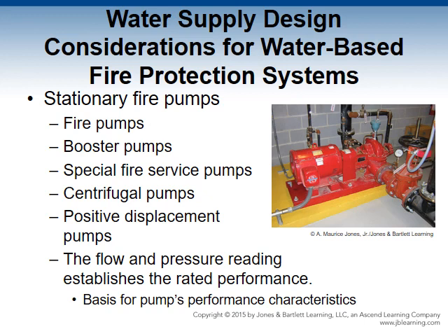Stationary fire pumps. When water-based fire protection systems have adequate supply but need additional pressure and flow of water, the stationary pump is usually the first and obvious option. The fire pump has replaced the gravity tank and water booster pumps as the most common method used to pressurize a water-based fire protection system. Fire pumps take water from a source and boost the pressure to the desired level. Additionally, a fire pump delivers a certain amount of flow to the water-based fire protection system.